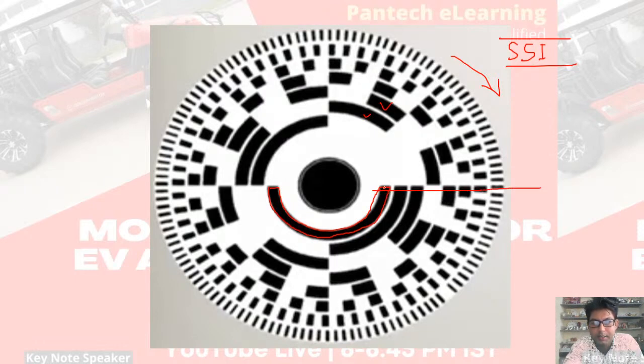So say it is in this position. Say this is the MSB and this is the LSB. Now for this particular position, that photo detector will detect the LED, because these areas are empty. So what will we get? 1 1 1 0 1 1 1 0. You got a bit sequence. So here it is 1 2 3 4 5 6 7 8 bit.